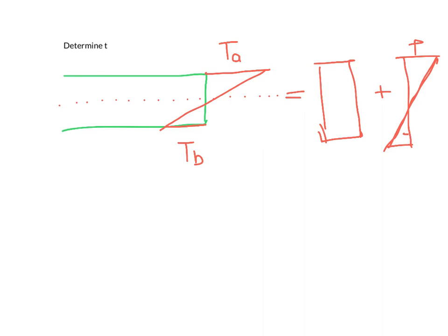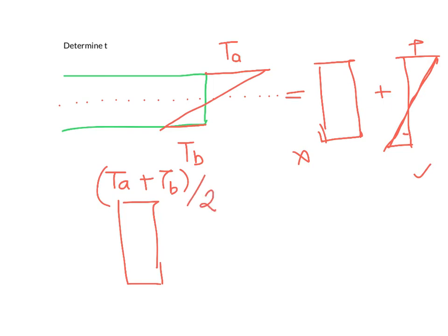Now here, if you dissociate this Ta and Tb increments in two temperatures, this uniform temperature will not result in any warping, but it will give a pure bending. So this temperature is not responsible for warping. This is the temperature which is equally positive and negative at the top and bottom of the pavement, and is responsible for your warping. So this uniform temperature can be given by Ta plus Tb by 2.